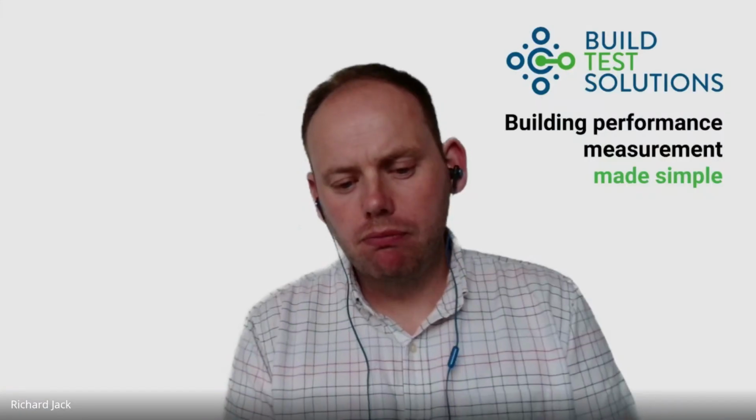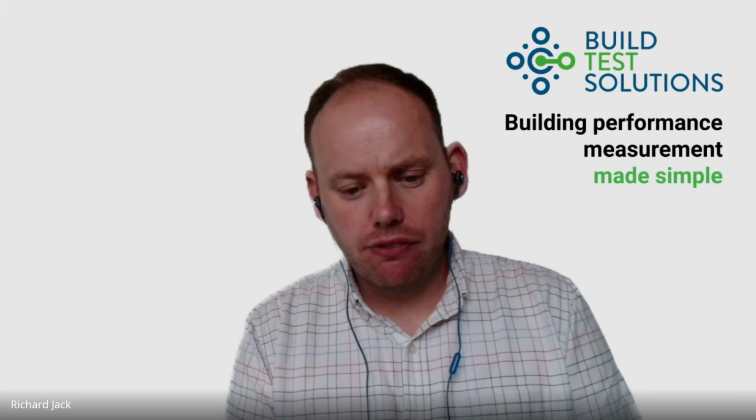So if you're trying to size a heat pump to cool a whole house and reverse it and heat in the winter, that probably means you have to settle for a fairly inefficient larger heat pump for your heating demand. But yeah, there's a bit of a practical issue with, we're mostly having wet heating systems, much harder to distribute cool than an air-to-air unit.